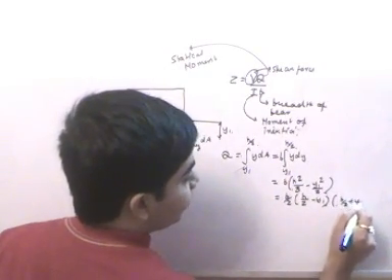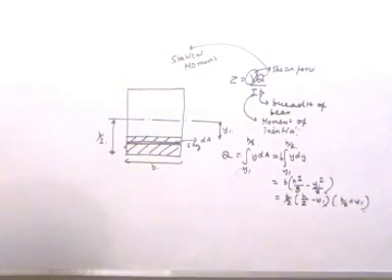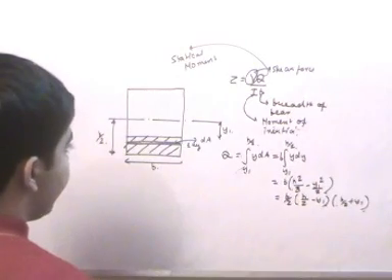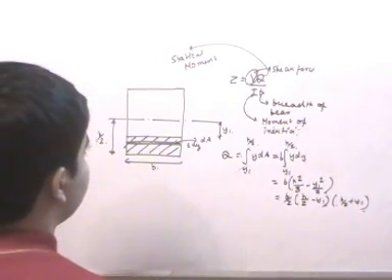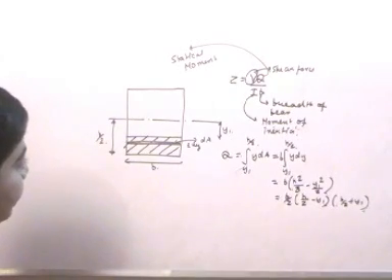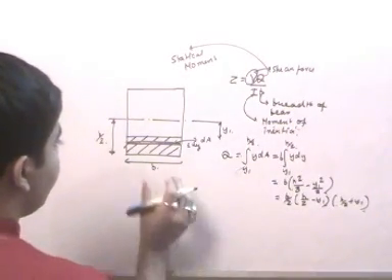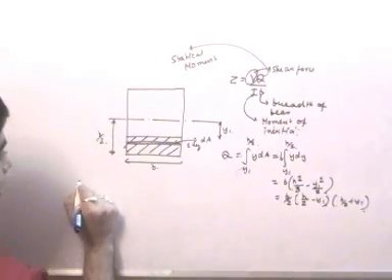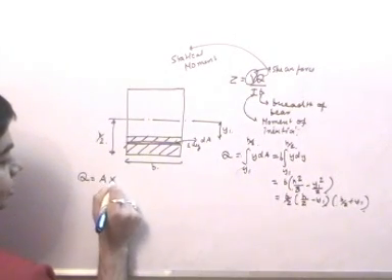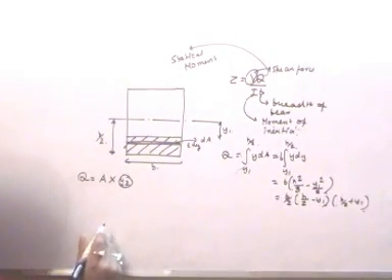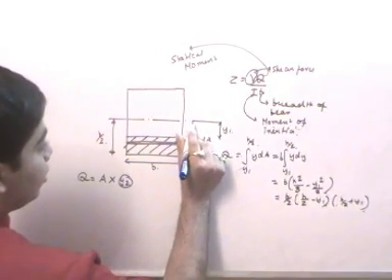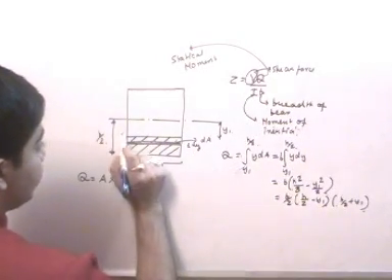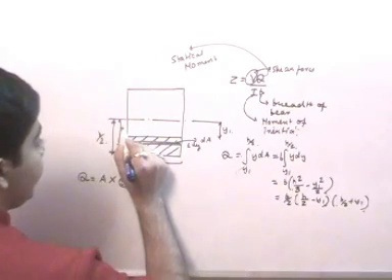or b by 2 is equal to h by 2 minus y1 and h by 2 plus y1. Now, what is the physical significance of this statical moment? We have this elemental block and we considered equilibrium of this elemental block. Now, the statical moment will give us the moment of this elemental block with respect to the neutral axis. So essentially, Q will be the area into y2, where y2 is nothing but the distance of the centroid of the neutral axis from the CG of this elemental block, and therefore this suppose is y2.